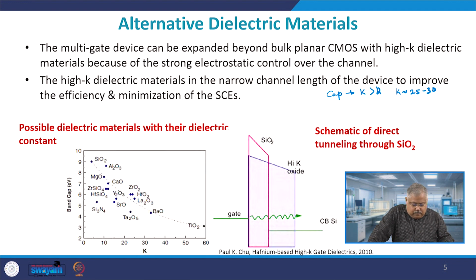Now, typically what happens is that if you take a very large K dielectric, you then end up having a large fringing field, which adds to the capacitance value. So, these parasitic capacitances tend to reduce or degrade the dynamic performance or transient performance of the device. So, you need to play with all these factors in order to ensure that the device is in the proper state.